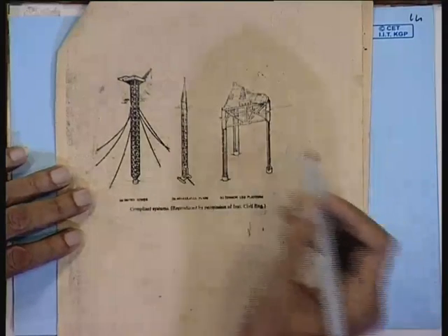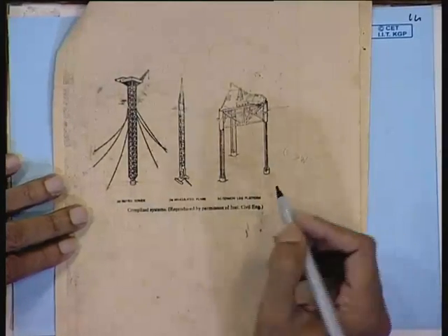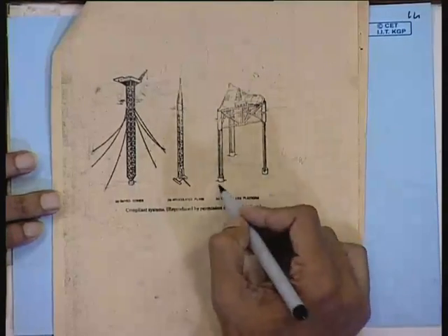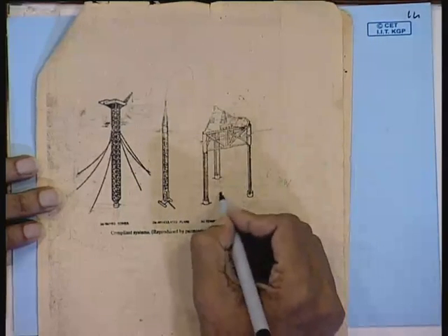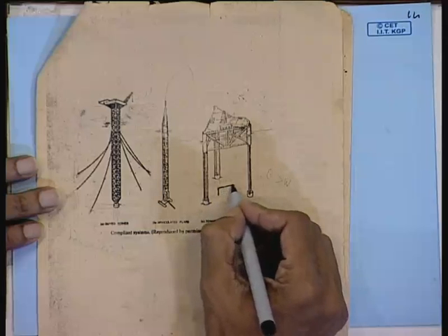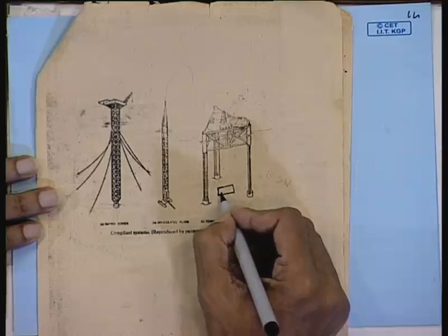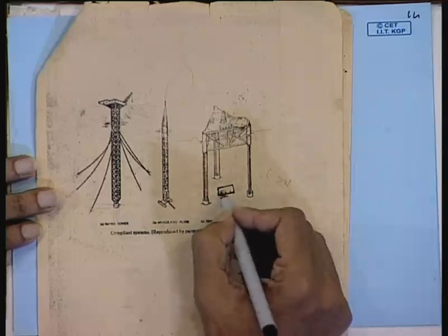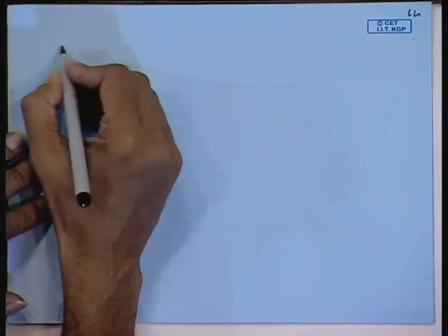Now, here you note that the three types that have already been discussed are the guide tower, then articulated flare, which is just for igniting your gas, and the TLP. Now, in this diagram of the TLP you can see the foundations, but what is not shown is the template. Now, template will come somewhere here, and that is actually the suspension of the pipes. This is called template or a wellhead assembly, which suspends your casings. So, your template is actually a suspension point for the casing string.